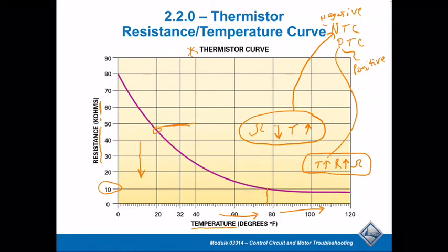That's typically, most of those thermistors are operating under a very low voltage, but we use a lot of them. So the manufacturers can design a circuit board to look at the resistance change. And what they're really doing is sending a small voltage through the thermistors and looking for what the current draw or the voltage drop coming back is. So in the circuit, that's how they use it. That's how they determine whether it's 72 degrees or 80 degrees or 90 degrees.